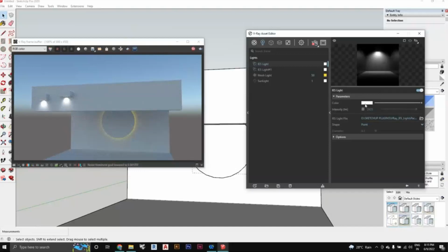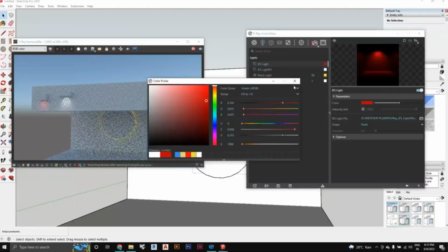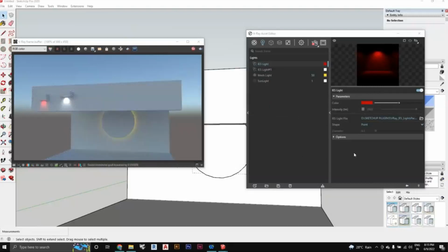And you can also change the color of it. You can press on it and change the color, whichever color you want, and then you can go back. This is also possible in options similar to our spherical light or omni light. You can basically change the diffusion as well as the specular in this room light as well. This is what I needed to teach about the IES light.